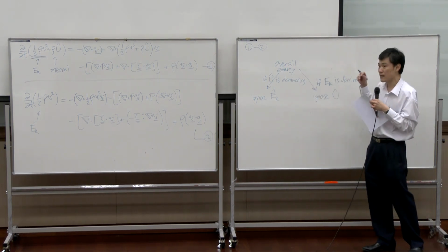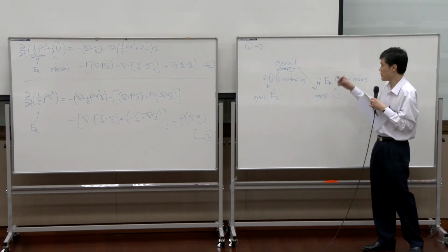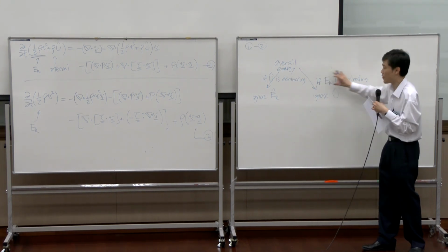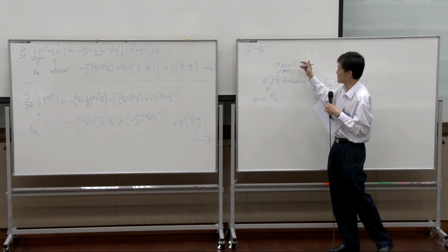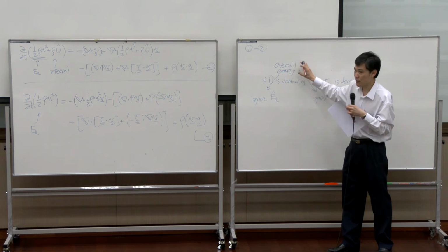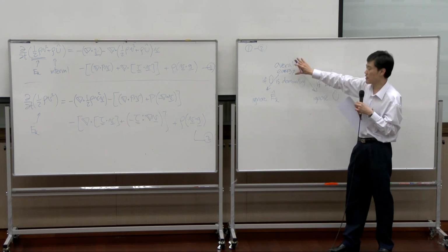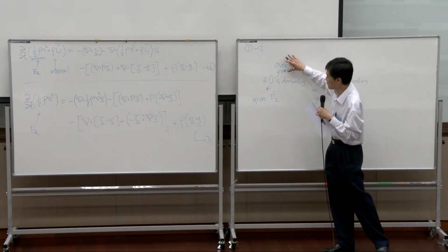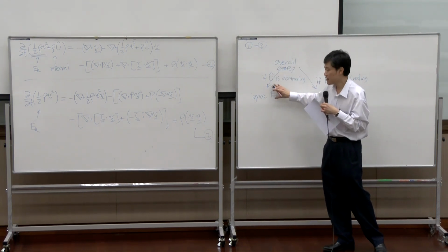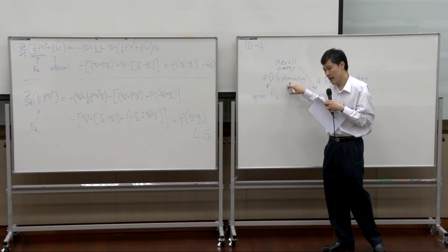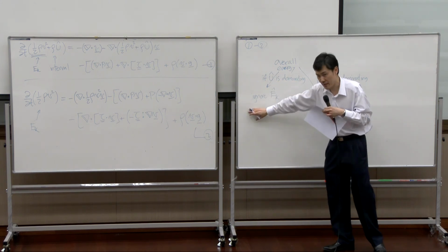But when you change, like you put the pump into the flow, velocity change, kinetic energy is dominating, you take this route. Okay, so on one hand, you have overall energy balance that you learn in principle of calculation in chemical engineering. It would be easier to ignore one term, ignore kinetic energy, if U is dominating. This one you took in thermodynamics.